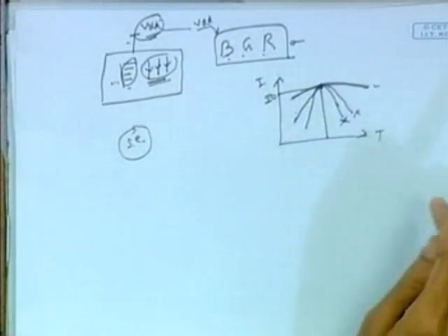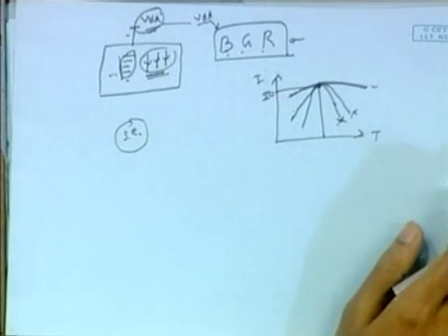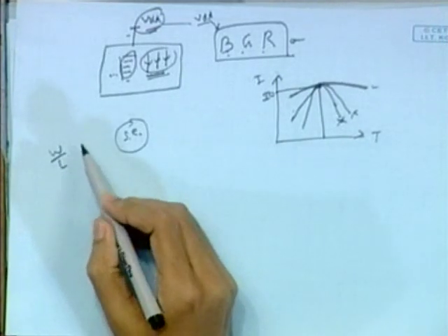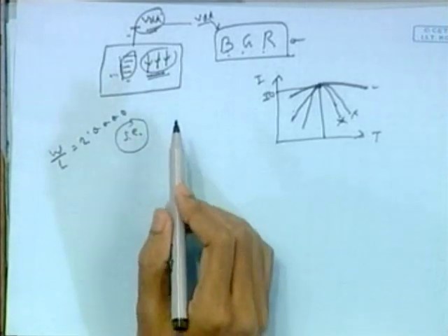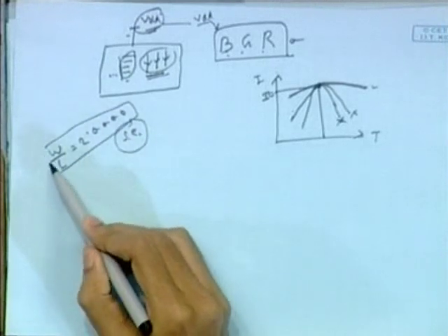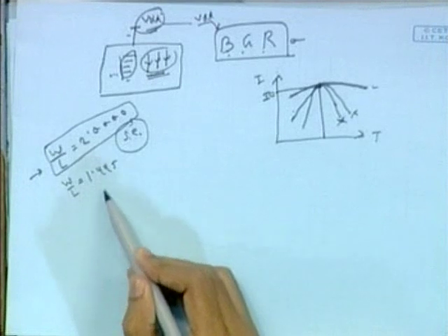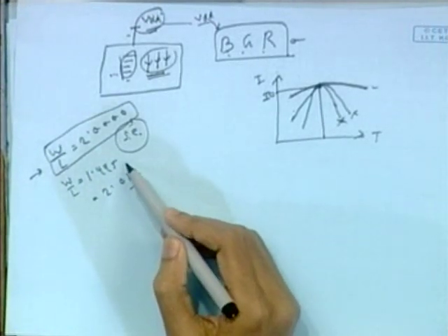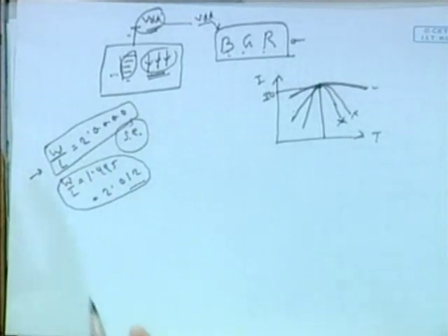And also you may be aware that there is a term called process corner variation. Suppose we have designed a W by L ratio of a transistor as 2.000, a perfect 2, but this is a mathematical singularity. No process can guarantee that your W by L will be 2. It may be 1.995, it may be 2.012, like this. So there is a variation of your design parameters while fabricating the IC.